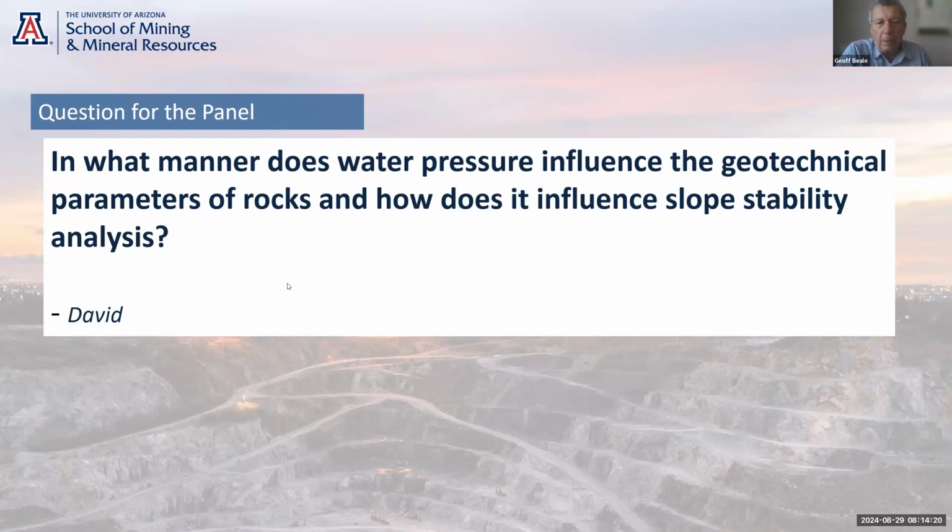So I always say it's a simple concept that's made complicated by geotechnical engineers, but it is really a simple concept. And, you know, it applies to any situation. So it's any shear surface, any medium, if it's got water in it, it reduces the shear strength. It is detrimental to stability. So that's the main thing.